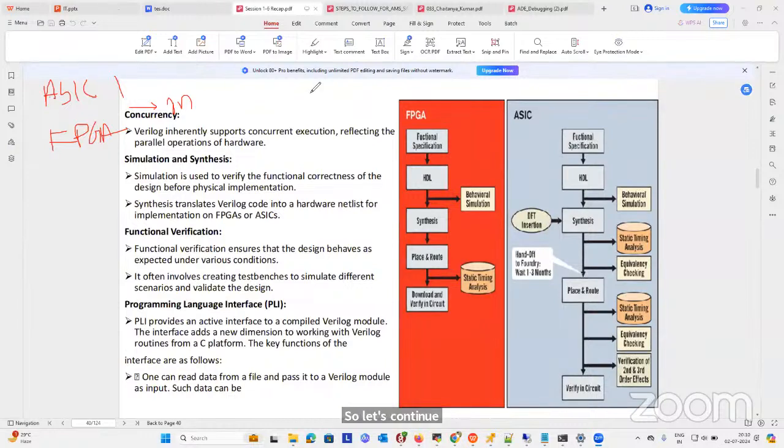So we are understanding about FPGA and ASIC. When we want to design an ASIC chip, it is only a one-time program. That is, directly we are doing the layout and GDS. Whereas FPGA is like a microcontroller board, we have field programmable gate arrays where we can upload our logical Verilog code after synthesis.